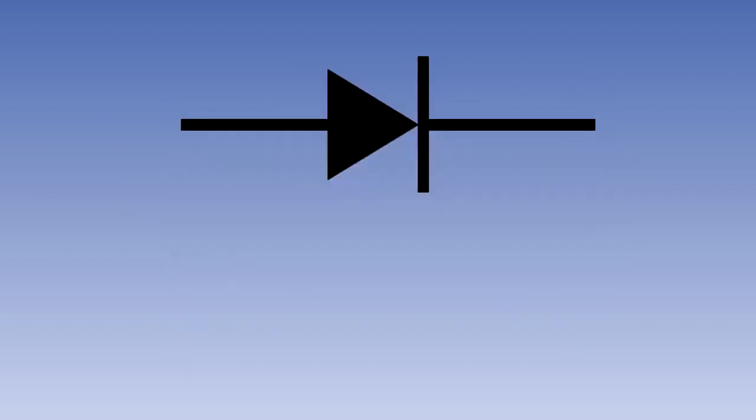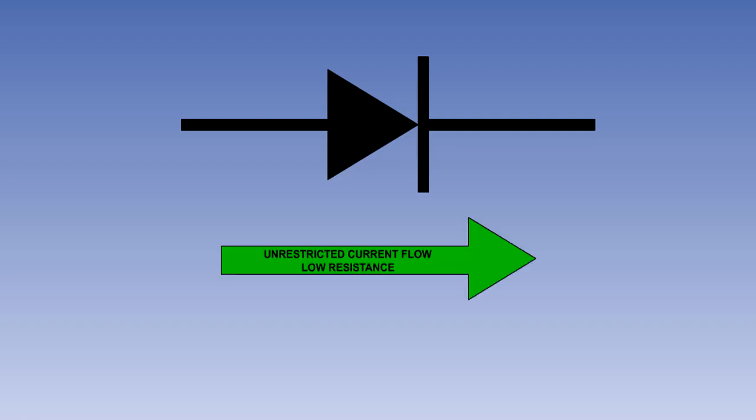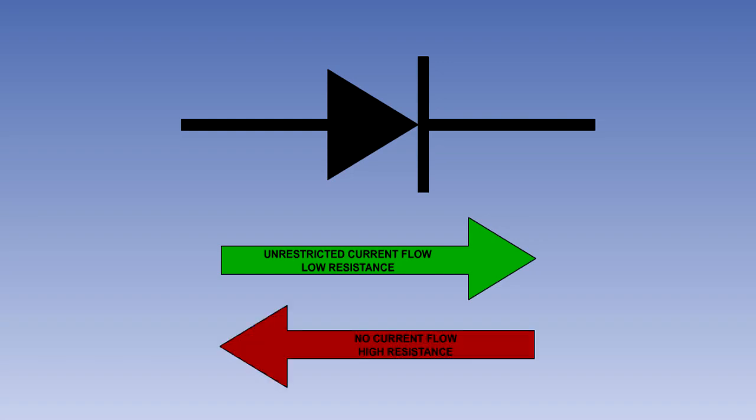The era of solid-state electronic components has led to the development of the high-current diode rectifier. This is a solid-state device with no moving parts. Its electrical symbol is shown here. When placed in an electrical circuit, the diode rectifier allows current to flow unrestricted in the direction of its arrowhead, but blocks flow in the other. This means that the commutator is no longer required, as the generator's output can be converted to DC externally to the generator.